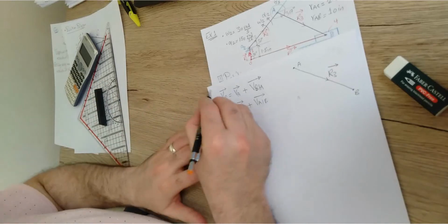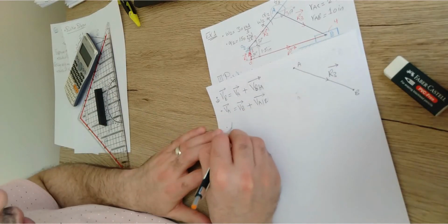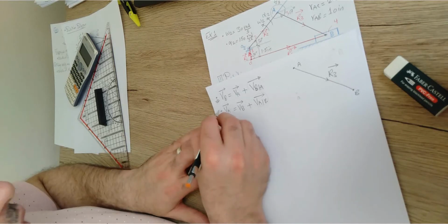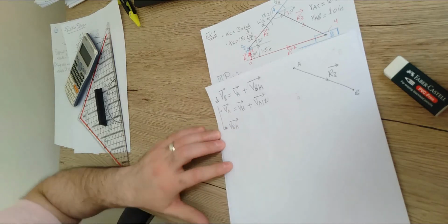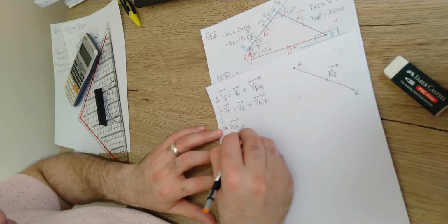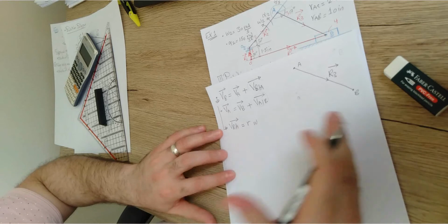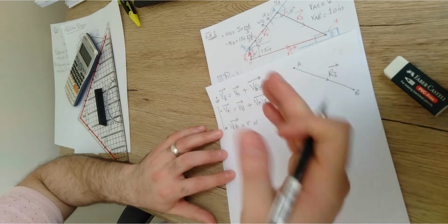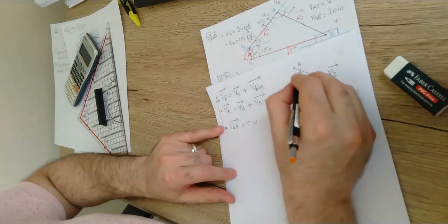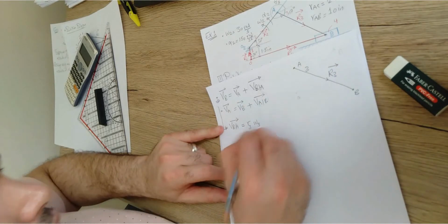So for example, let us proceed with the first one. It means that I'm going to work on the VB relative to A vector, right? So I'm still working over the same link. For the VB relative to A vector, you should understand that the magnitude is R times omega, and its direction should be perpendicular to R and rotate in the same direction as omega 3. Here we are working over link 3, so it has R3, and this should be R3 omega 3.